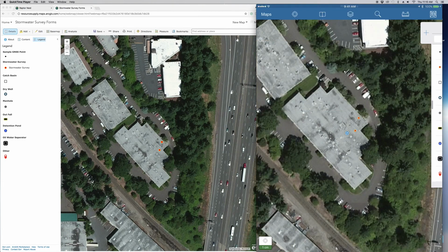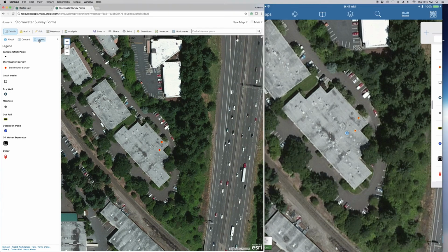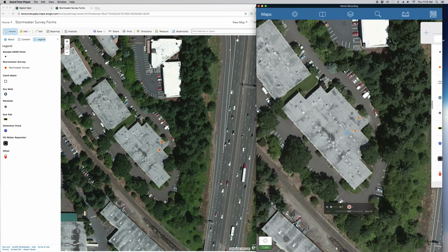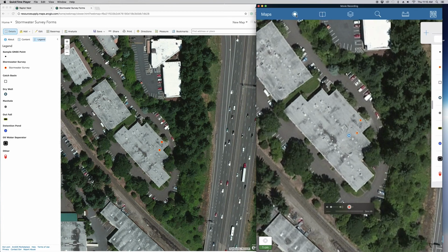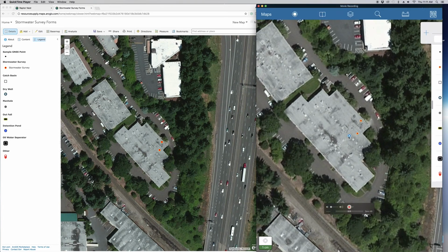So basically, your project data and your data collection forms, you have to push it from your GIS database to your ArcGIS Online account, and then with the same login, you can log into your iPad device in Collector and view project data and collect data. So what I want to show here very quickly, it's very simple to collect data. I'm sorry, it actually zoomed onto our position. So now we're using where we're standing right now for our position.